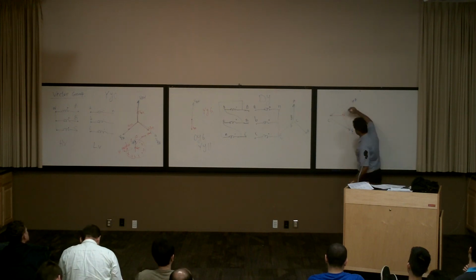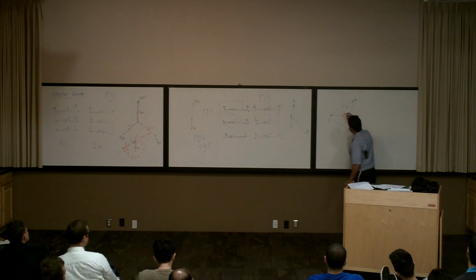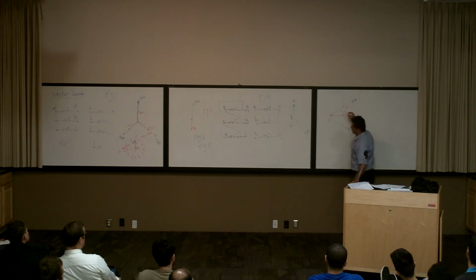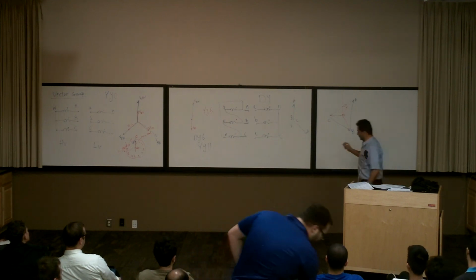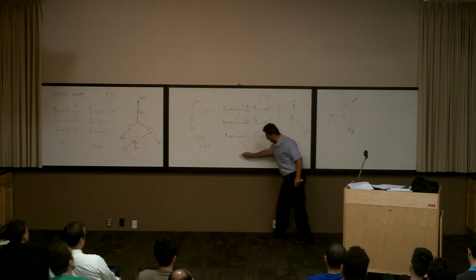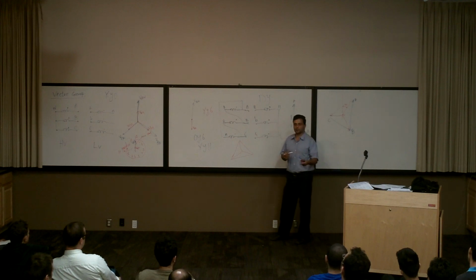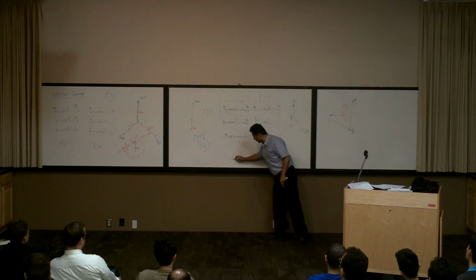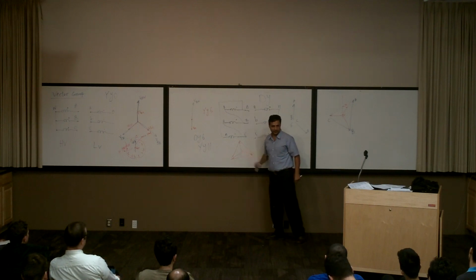Can somebody tell me how much is this angle? 120, right? How much is this? 90. How much is this? 30. So basically, I want to find where the phase voltage is. That was my intention, to put it in a triangle, because when I have a delta, it's very easy to find the other. Remember we said delta to star conversion, Y to delta. So these are my phase voltages. If I know this triangle, easily I can connect them like this.